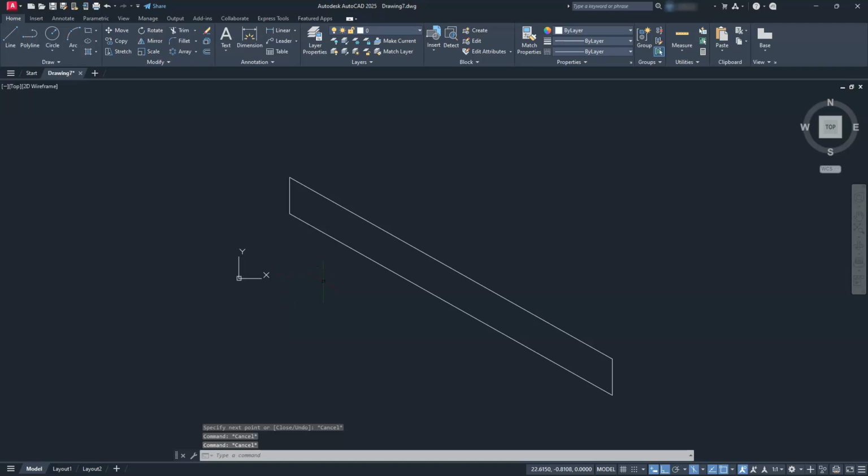Okay, so now I've completed this. I just left the chamfers off, right? I need to shorten these two in order to include that chamfer that I want to put on here. So all I got to do is select this line here. I'll grab this grip. I'll drag back this direction and type in 10. Likewise, going this direction. Okay. Now I can grab these lines here, and I guess I could have stretched them both together, but I'll just grab them here and place them on the end points of each other. All right. So this is basically that bottom base of what you're going to see.